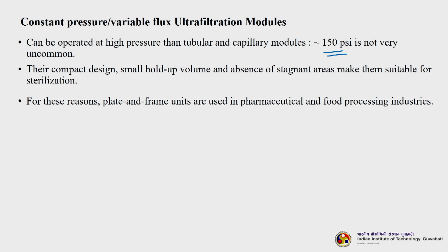Their compact design, small hold up volume and absence of stagnant areas make them suitable for sterilization. When you are doing bioseparation applications, that means you are purifying or concentrating proteins, then sterilization of the modules as well as membranes is a must. So, they are sterilizable. This is one of the beauties of plate and frame systems. For these reasons plate and frame units are used in pharmaceutical and food processing industries.